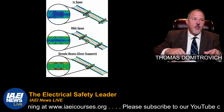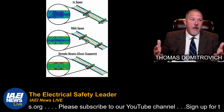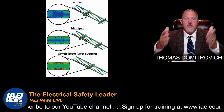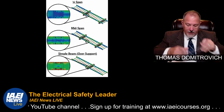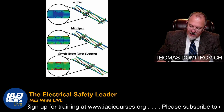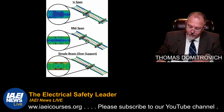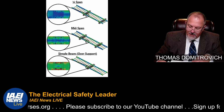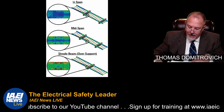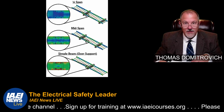Now, a manufacturer can offer different lengths. So you might find a manufacturer that does 40 foot or some other distance. But for the NEMA standard lengths, there are two documents referenced in Article 392. There's NEMA VE 1, Metal Cable Tray Systems, for further information on cable tray. There's also NEMA VE 2, Standard for Installing Metal Cable Tray Systems.